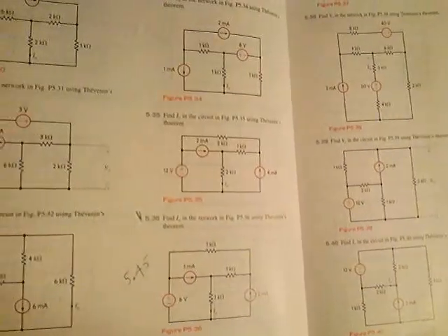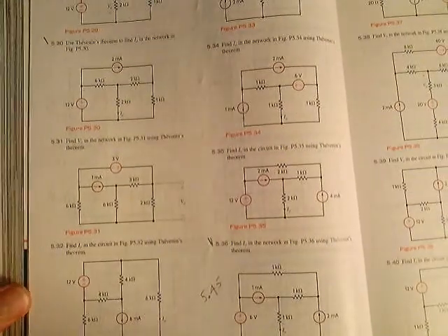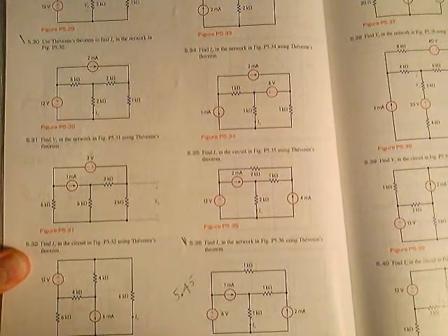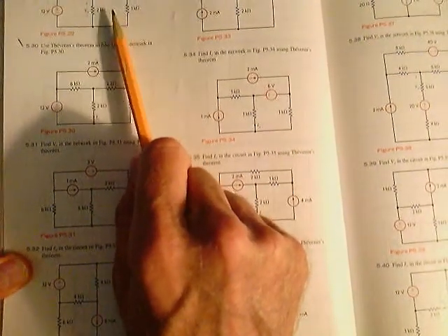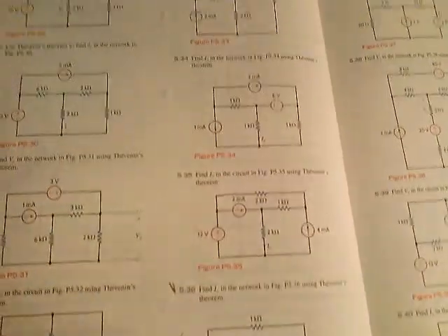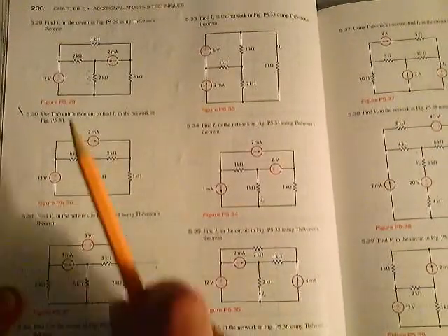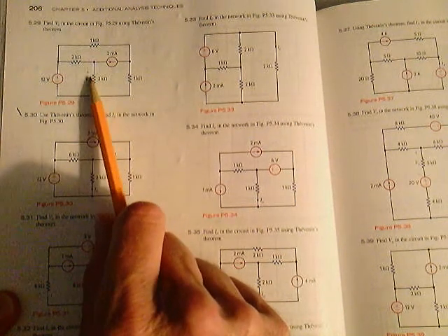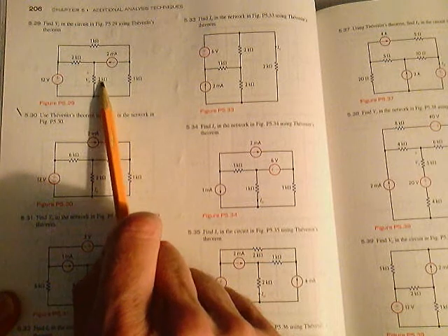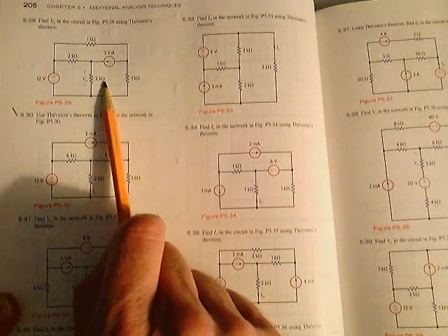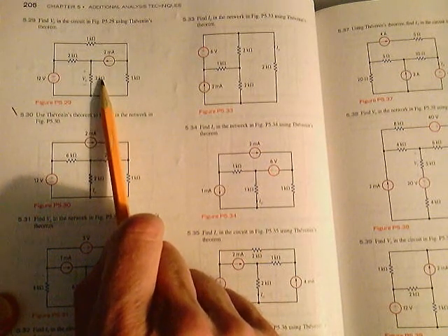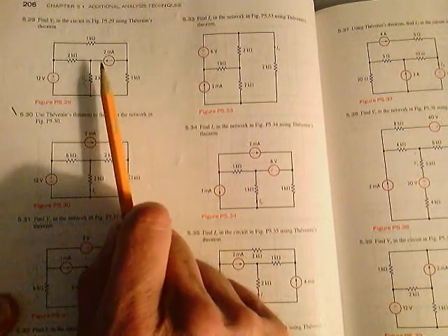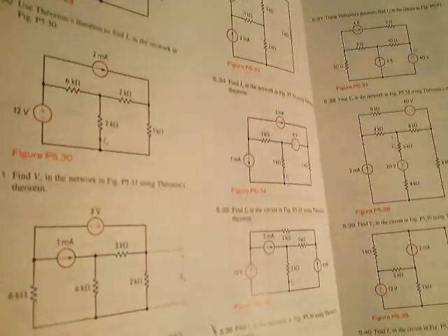These are going to be homework problems. Some of the problems we're going to work out. Some of them will be homework. But if you look here, in this problem up here, 529, Problem 529 here says we want to find an equivalent circuit for V out. In other words, we're going to take this 2K ohm resistor here, we're going to treat it as a load resistor. We're going to remove it, and we're going to look back into this circuit, and we're going to simplify it down to something that looks like this.